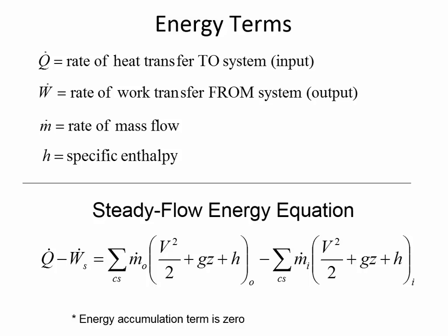We don't usually have to worry about the temperature of the liquids changing in a system like this. The pump gives off a little bit of heat. The temperature change of water as it goes through a pump is essentially negligible. It's very difficult to measure how much warmer the water is as it flows through a pump. And so we usually don't have to go so far as using this version of the energy equation. This version of the energy equation is saying let's even account for the specific enthalpy of the fluid.